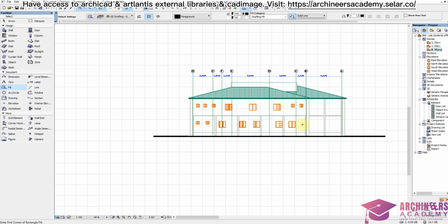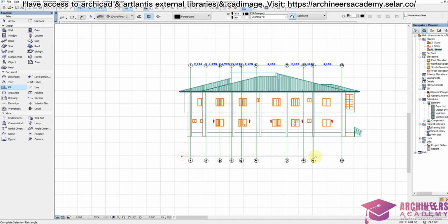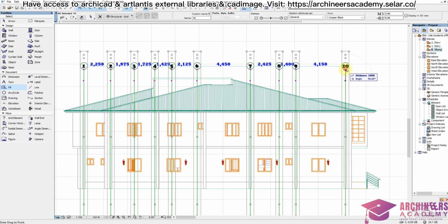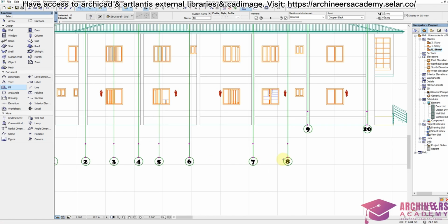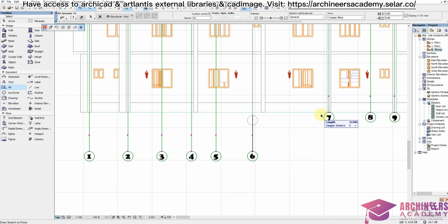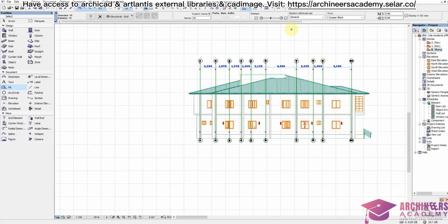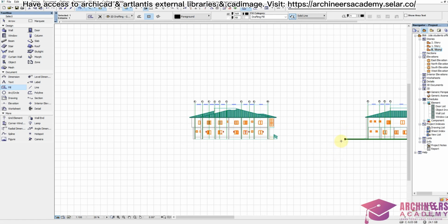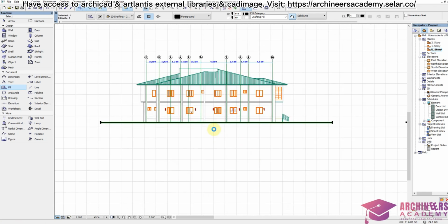Then right under here, back elevation. We can repeat the same process here. And drag the elevation up to cover or above the dimensions. Drag this too. Then we remove the down numbers, then Ctrl Shift D to place a ground level here also. So that is a simple way of finishing your elevation after writing down here, which is called back elevation, and you are done.